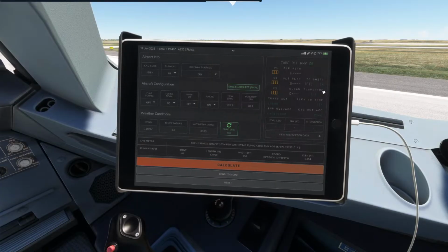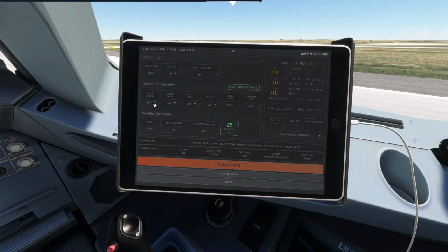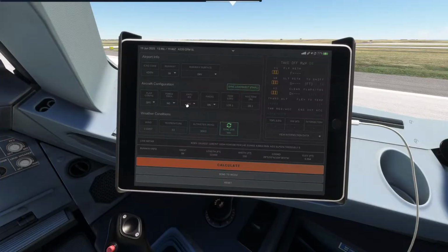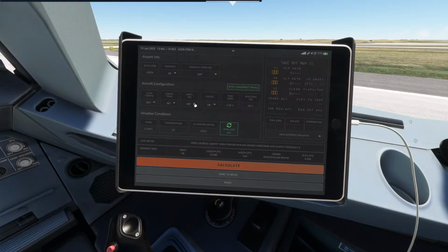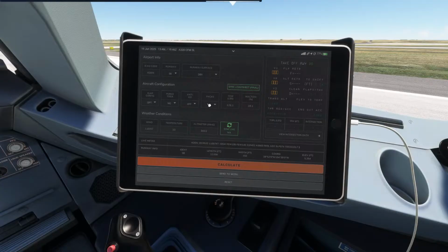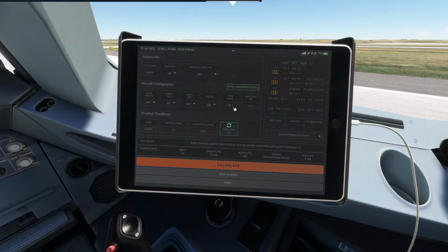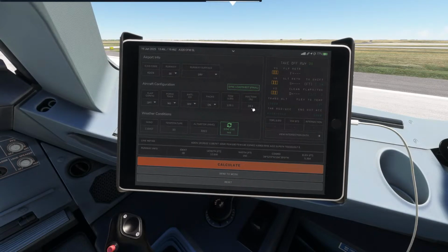So basically, your zero fuel weight plus your block fuel weight is our current takeoff weight, which obviously is going to be less. We're going to burn some fuel, but flap config optimal. Forced toga means that you're just going to take off with max thrust, so we're going to put no. Anti-ice is off. Pax will keep on, although the density altitude is probably pretty high, so we'd probably take off with Pax off, but who cares? It's fine. So here's my takeoff weight, 128,100 pounds.